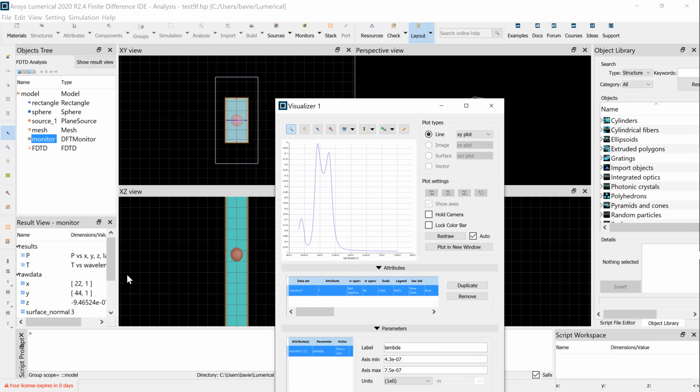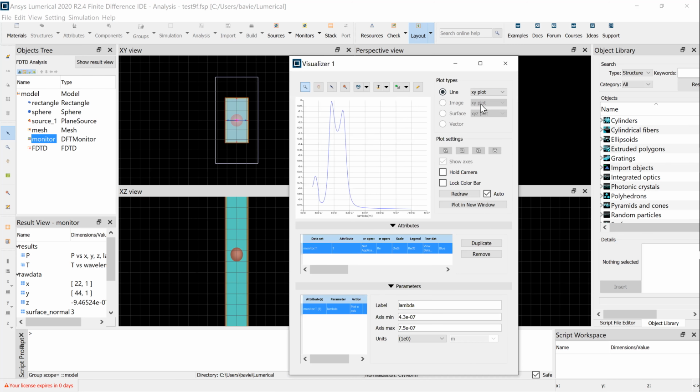It's called Visualizer. There are several places to pay attention to. We still keep the default XY plot here. Next, in the bottom section, we see some characteristics for this line. We need to select absolute value instead of the real part, because we are looking for the total transmission. Now the plot appears flipped in comparison to the plot of the real value.